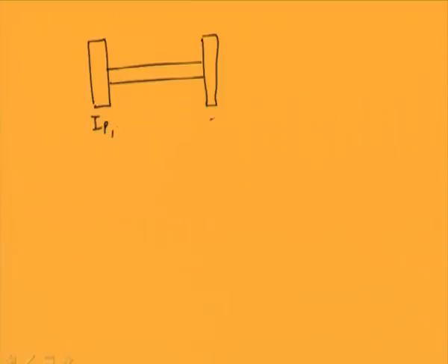Let us say these are the polar mass moment of inertia of the rotor, which is supported on frictionless bearings, so it can rotate freely. This is the length of the shaft, which is massless. The other properties of the rotor are the modulus of rigidity and the polar moment of area. This particular problem we can solve by assuming a single element like this.